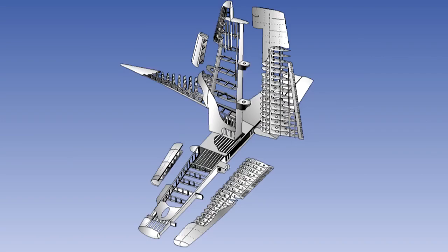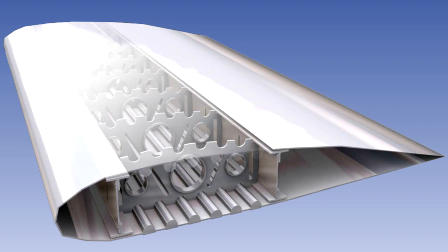Both the tailplane and the fin are subject to similar but smaller bending and torsional stresses as the wing. Structurally, the tail unit components are generally smaller versions of the wings, in that they use spars, ribs, stringers, and skin in their construction. On some aircraft, they may also contain sealed compartments for fuel storage. They are also constructed of the same basic materials as the wings. Usually, aluminium alloys are used, with composites filled with honeycomb structures or high-density expanding foam sometimes being used for control surfaces to provide greater stiffness at low weight.